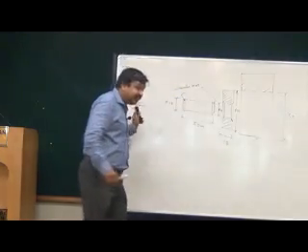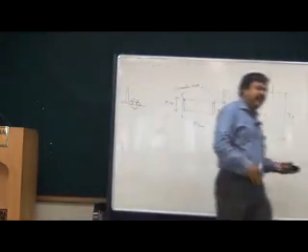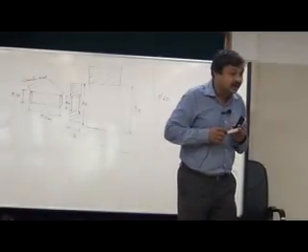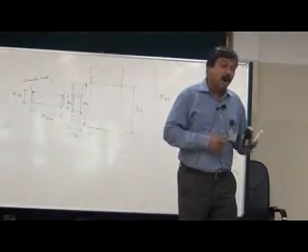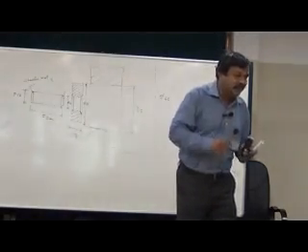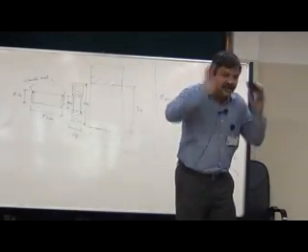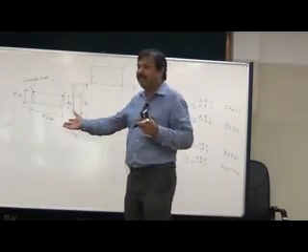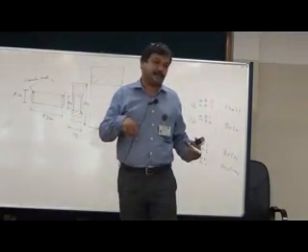So again, an interference fit can be attained. This is called a shrink fit. When you heat it and then apply an interference fit, it is called a shrink fit, because you make it shrink and then the fit is tight. Or I can get a dry fit. What is a dry fit? You hit it, drive it hard, you drive it inside. It is called a dry fit. So there are many types of interference fits. Similarly, there are many types of clearance fits.